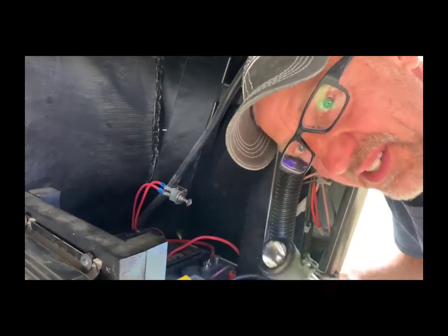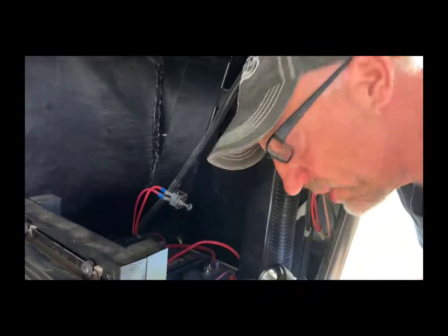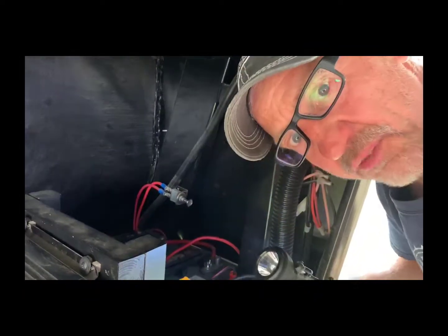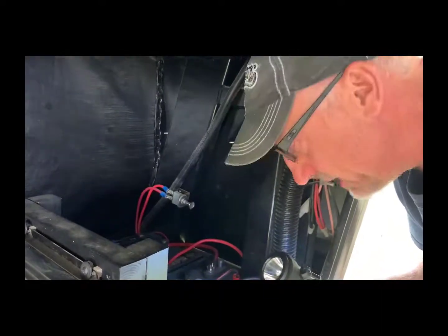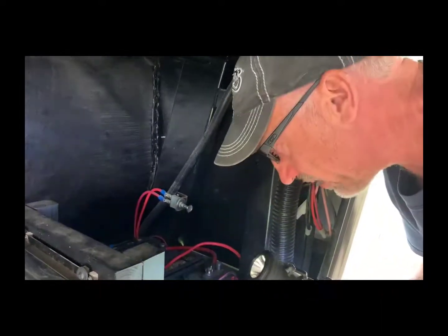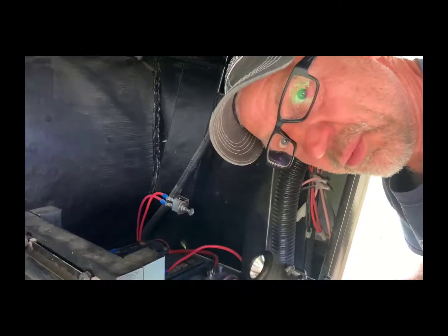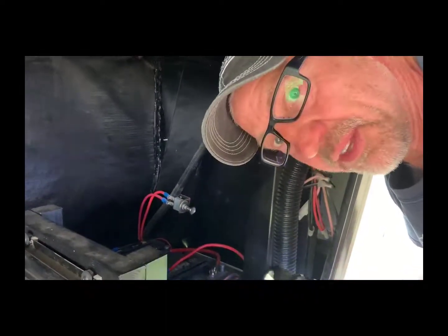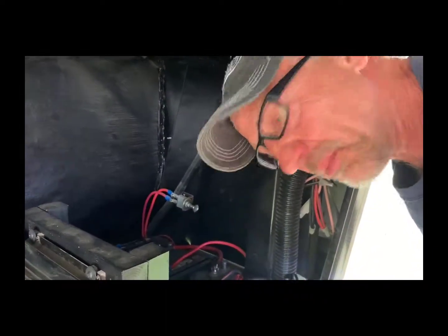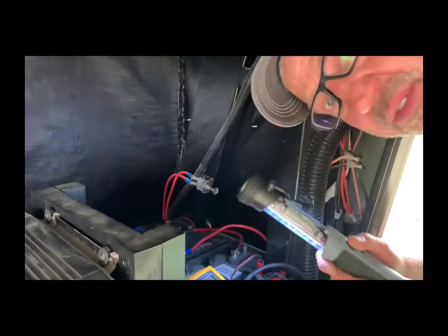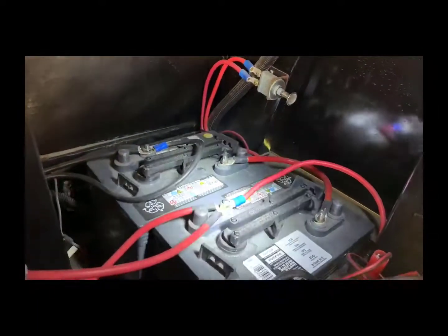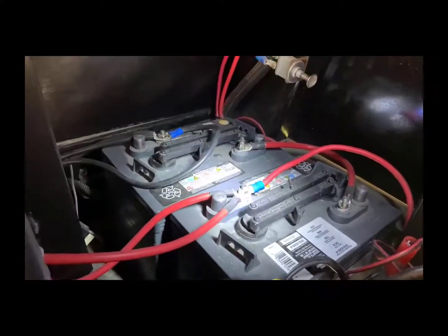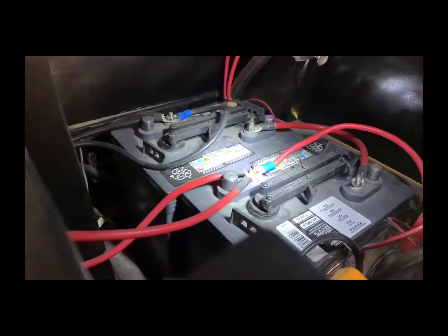Hi everyone, I thought I'd just take a minute here to show you in reality voltage sources connected in series to give you a greater voltage, but the current available would be the same as from just one battery, because there's only one path for current flow. So if we take a closer look at these batteries in my RV, I've got two 6-volt batteries to power up a 12-volt system.